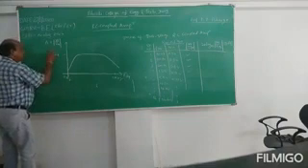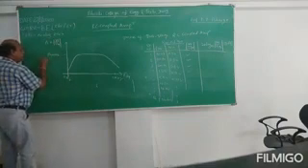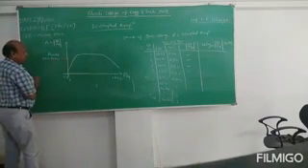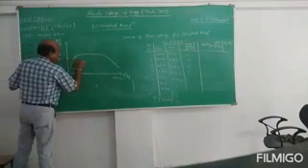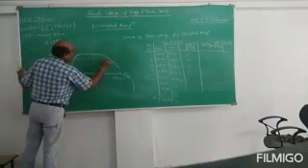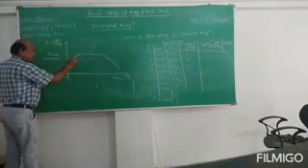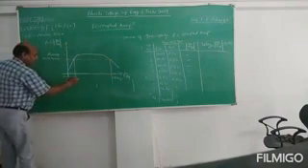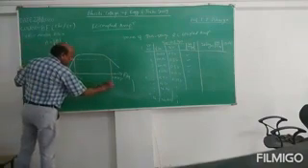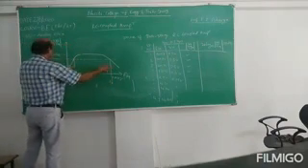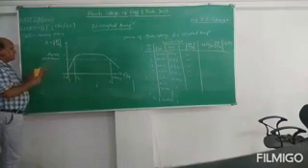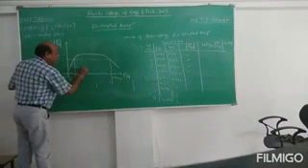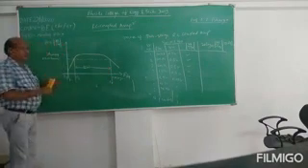And if this is in ratio, then multiply by 0.707 times A max. This will be here. Sketch a horizontal line with respect to 0.707 and you will get two frequencies here. This is one frequency, this is another frequency. This is FL and this is FH. Within this frequency range, the 0.707 times A max region is called the bandwidth. This is called the frequency response.